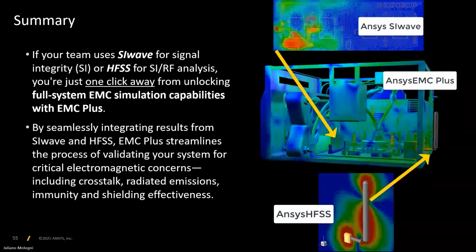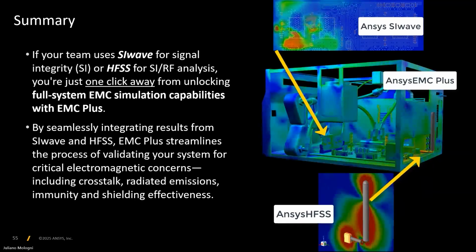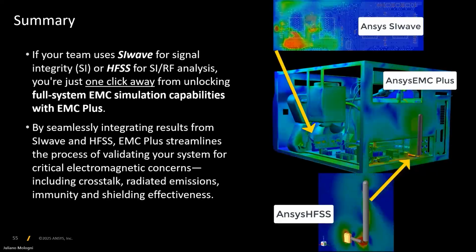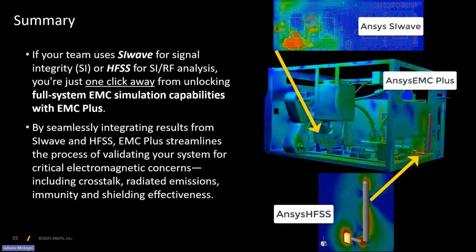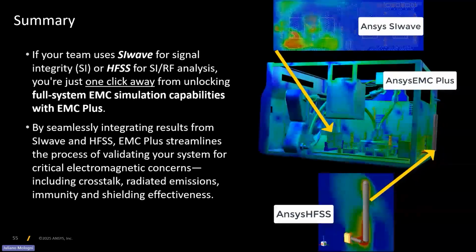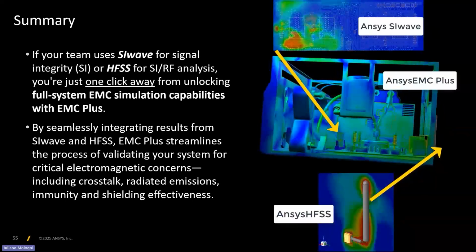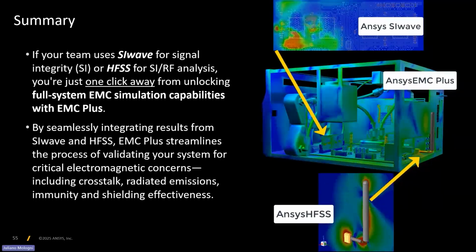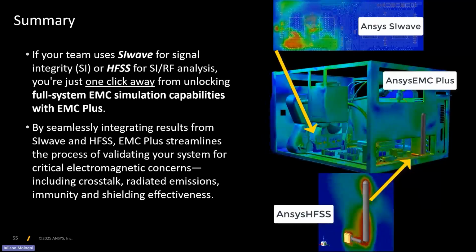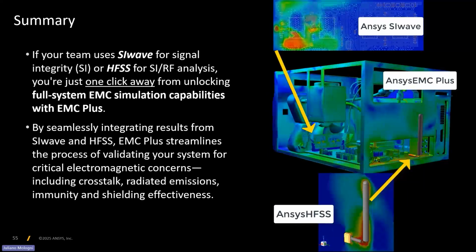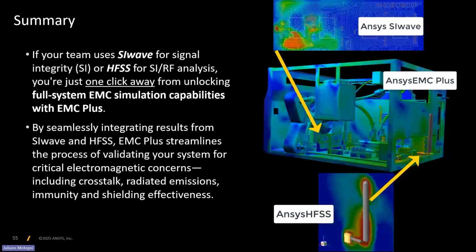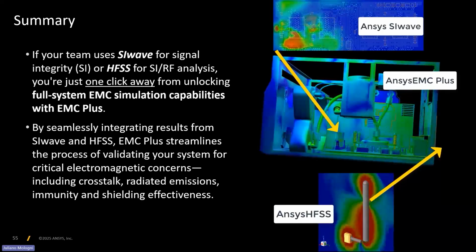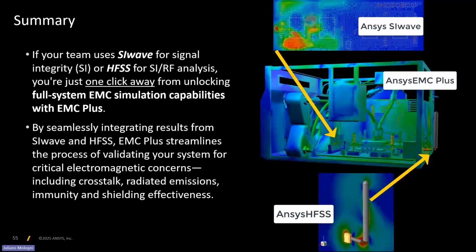Okay, and the next question is, if the CAD model doesn't have cables, can you recreate them in EMC Plus, assign cable properties, and run this as part of the simulation? Oh yeah, absolutely. We import KBL files, that already brings all the routing and the cross section of the cables. But basically, what you have to do in EMC Plus, you design a line or one of these tubes, like you're seeing here. You can extract a line from that tube, and you can right-click and specify your cross section. You can add conductors, you can add shielding, and you can connect the shielding. You can have pigtails, connect the shield to a 3D geometry. It's extremely flexible and easy to create cables in EMC Plus.